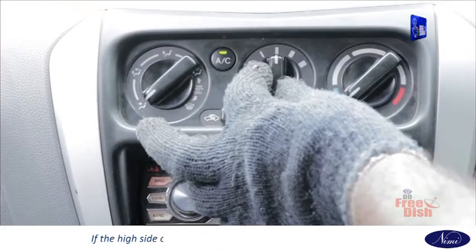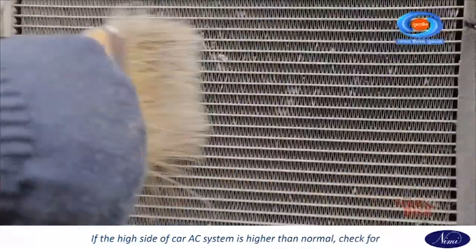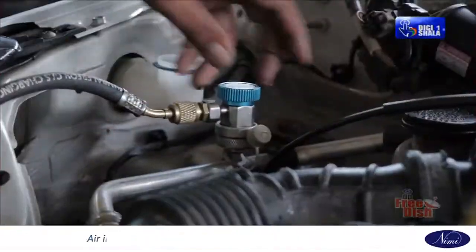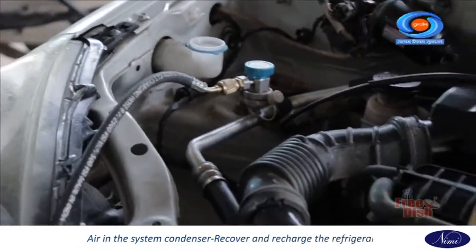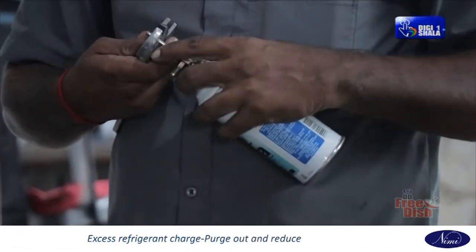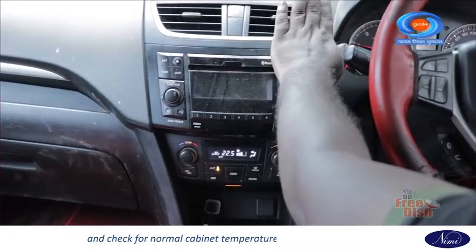If the high side of the car AC system is higher than normal, check for a dirty condenser and clean the condenser. Air in the system: recover and recharge the refrigerant. Excess refrigerant charge: purge out and reduce the refrigerant, and check for normal cabin temperature conditions.